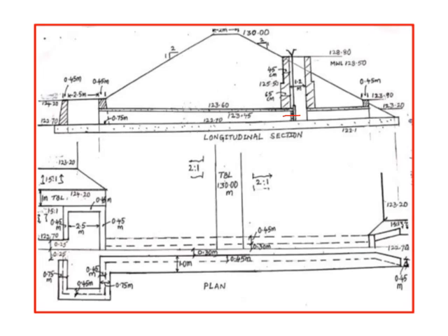I told you that the sill of the barrel is kept at 122.7, whereas the top of the RC slab is 123.6. We know the TBL is 130. We are given slope 2 is to 1. So we have fixed the top of the tower head at 128.8. So now you know that this is the top here after water flowing. So it has to go to the cistern. So now a cistern has to be provided.